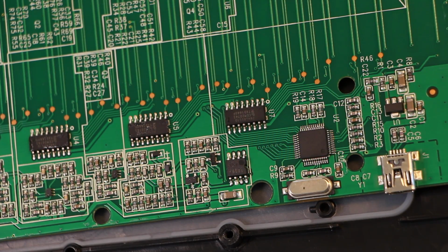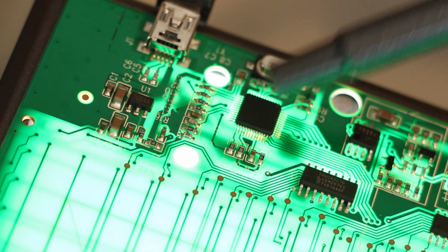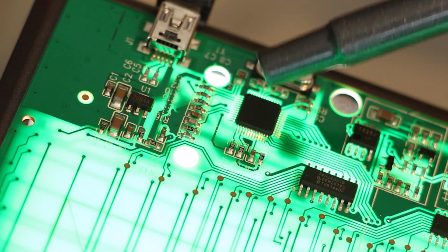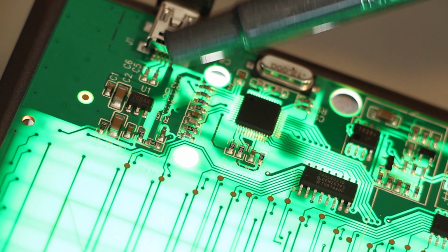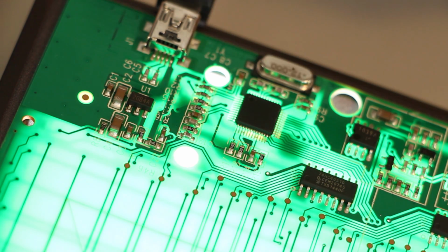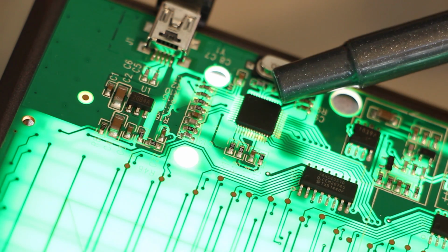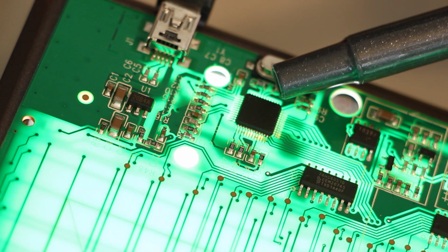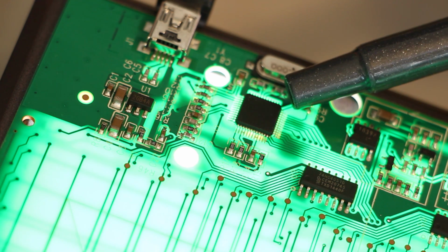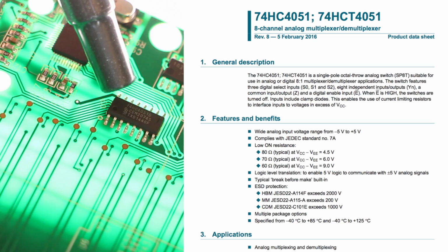Oh, there we've got our analog front end. This square chip in the middle without any markings will be our microcontroller chip. It's got a 12 MHz crystal and it's connected directly to the USB interface. Without the labeling, it's harder to tell exactly what this chip is, but it could really be any small microcontroller with a USB interface.